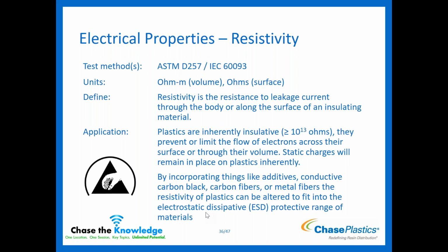Like we mentioned, plastics are inherently insulative. They don't want to conduct any of it, and so their values tend to be 10 to the 13 ohms plus. They're going to resist conducting it, so the value's higher. So what does it mean, being insulative? It means they're going to prevent or limit the flow of electrons across their surface or through their volume, or body of the part. That means if there's a static charge, it's going to remain in place on the plastic itself.